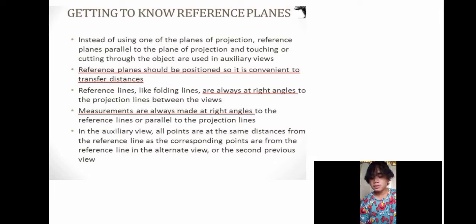Instead of using one plane of projection, reference planes parallel to the plane of projection and touching or cutting through the object are used in auxiliary views. The reference plane should be positioned so it's convenient to transfer distance.